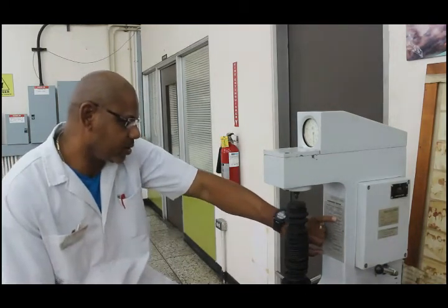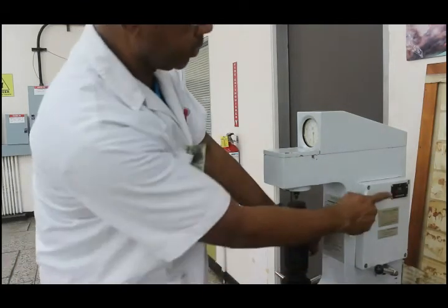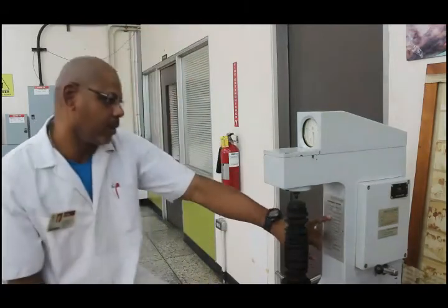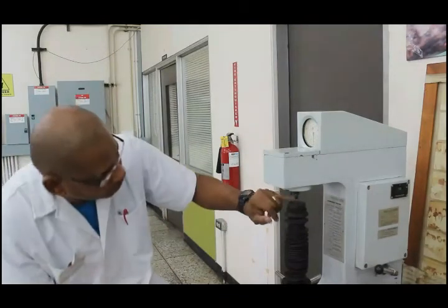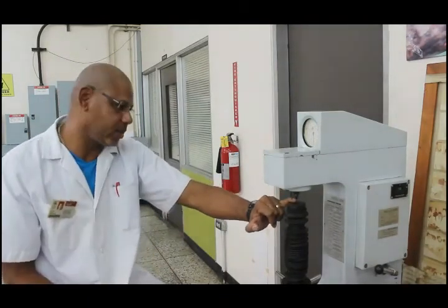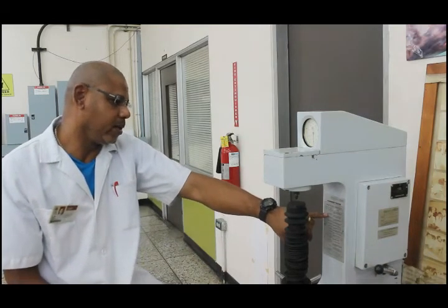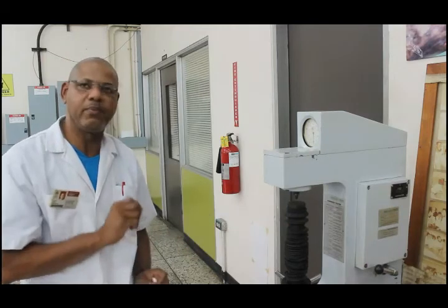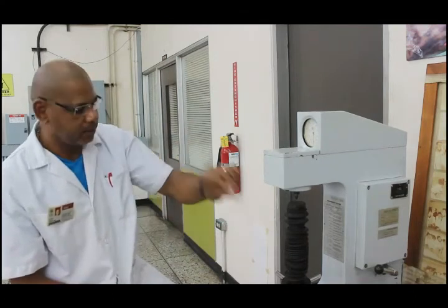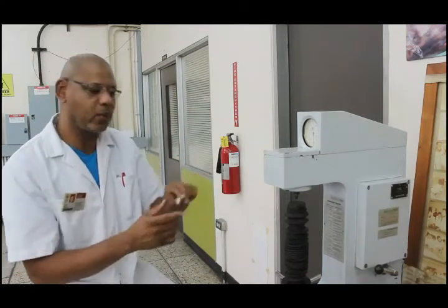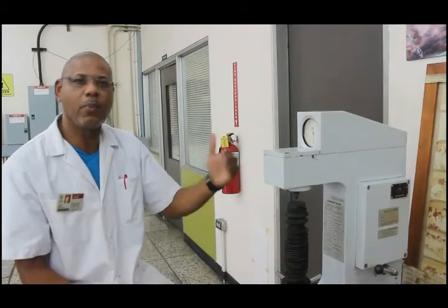So under applications, I've seen aluminum alloys, which will use a 100 kg load, which you would see there's a preset load of 100 kg. The indenter used is a 1/16 of an inch diameter steel ball. That's the indenter that sits here at the moment. It's scale 2 and the reading will be B. So all the readings we would put B in front of it so you will understand that this was Rockwell B79, so that no matter where these results go, you will understand what they mean in terms of what scales or parameters were set.